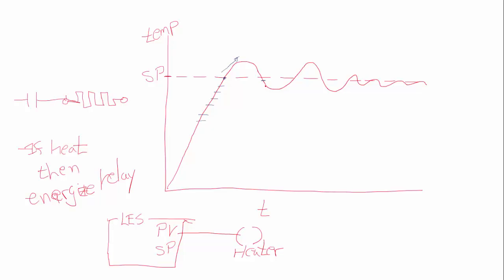So my temperature starts to drop. Before it starts to recover, the heater turns off, and that'll continue to do that all the way across to the point where we get the system that years ago they used to call a bang-bang system. And they called it bang-bang because the contactors were closing and opening and closing and opening and closing. Bang, bang, bang, bang, bang. Not very good for the contactors.